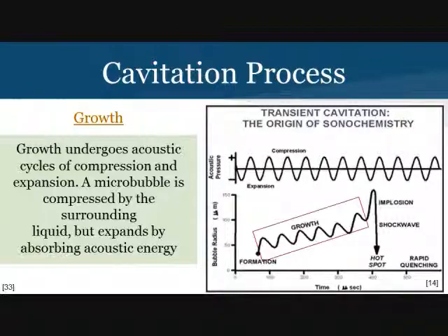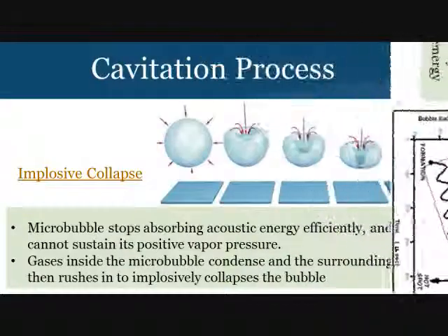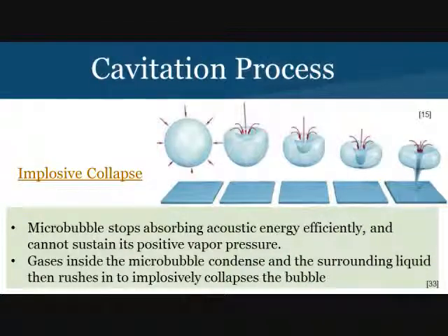Thus, the microbubble stores acoustic energy as it grows. There is a point when the cavitational bubble can no longer efficiently absorb acoustic energy. It is at this point where the microbubble is overgrown. The positive vapor pressure within the microbubble cannot withstand the negative pressure of the surrounding liquid.